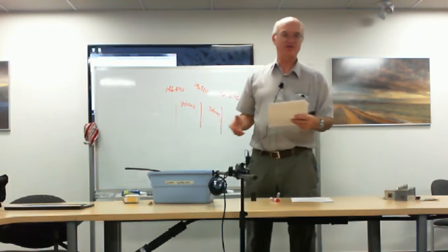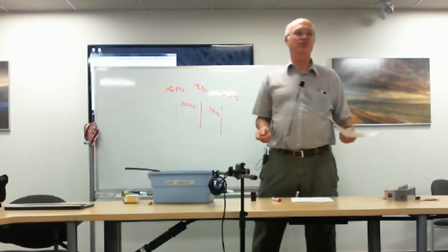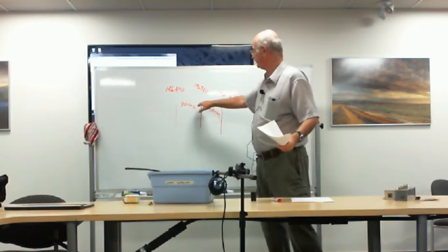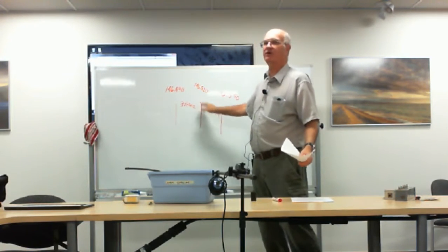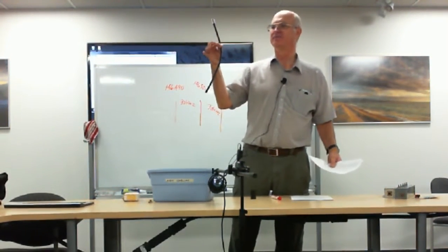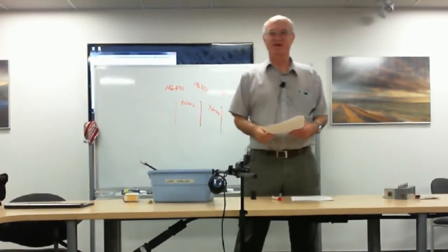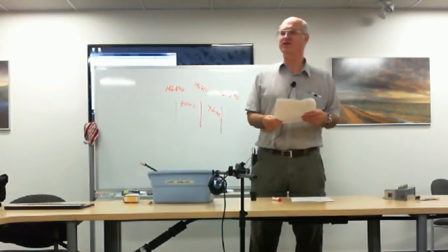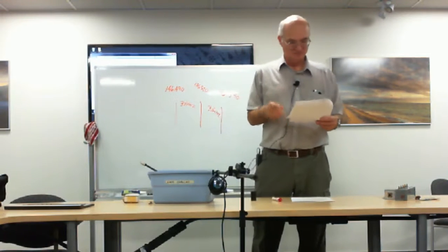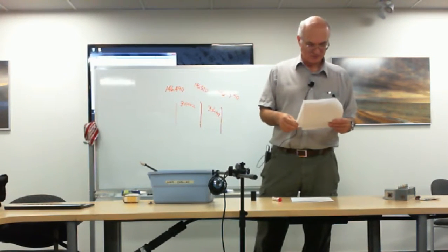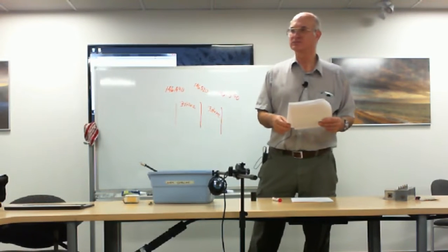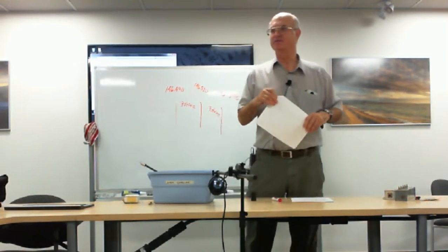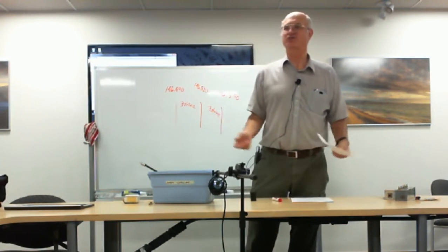So eliminating intermodulation, the only way to do it is either to remove the frequency or find a way to specifically filter out one of these. In the case of the pager, I did. I made it weak enough so it couldn't mix, couldn't get into the receiver and cause the problems. Remove the frequency or filter out one of the stations, if you can. If they're too close and too powerful, you'll have to move. You can only do so much with filtering.